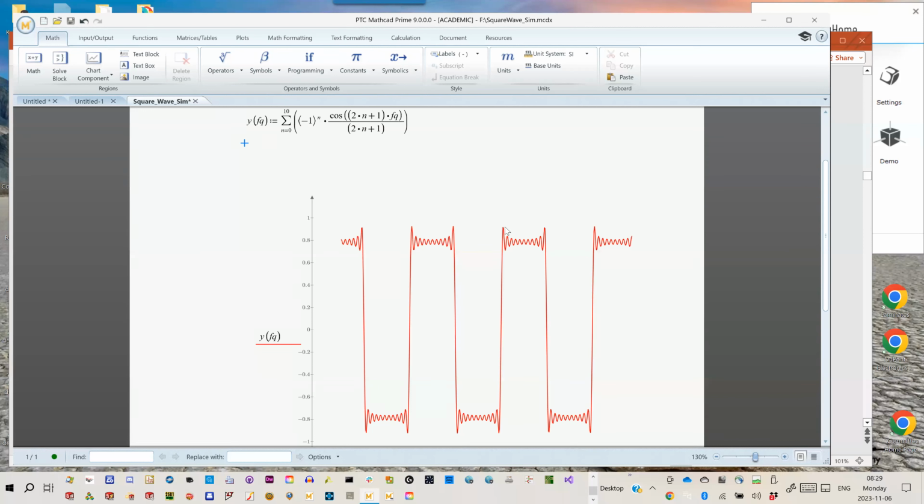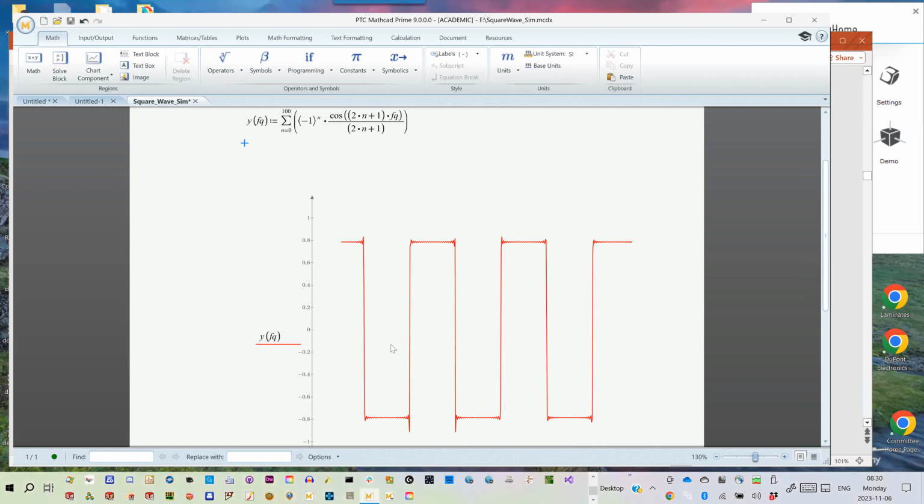As we shrink this silicon down, which we're going to see in the next slide, in order to achieve this fast edge rate, and let me just keep going here for a second, right? So I might have to have 20. I still have a bit of a slope edge right here. It's not vertical yet. So I might need to go to something like 50 or even up here to something like 100 to start to approach a vertical enough wall. Now that's the rise time. So if the silicon designers say this device creates a, say, 100 picosecond or 200 picosecond rise time because they've shrunk the silicon size down so much, that says you have to think about it in the reverse. If my rise time is that fast, my square wave is going to have this frequency content regardless of what clock speed. I'm going to have these higher and higher harmonics that must be present in order to have this.